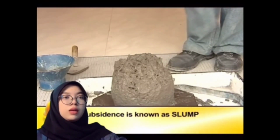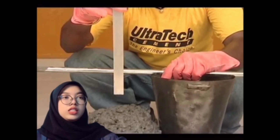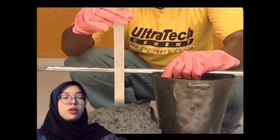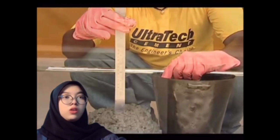The concrete will subside. This subsidence is known as slump. This operation shall be carried out without any jerks or vibration and within a period of 2 minutes after completion of final tamping.